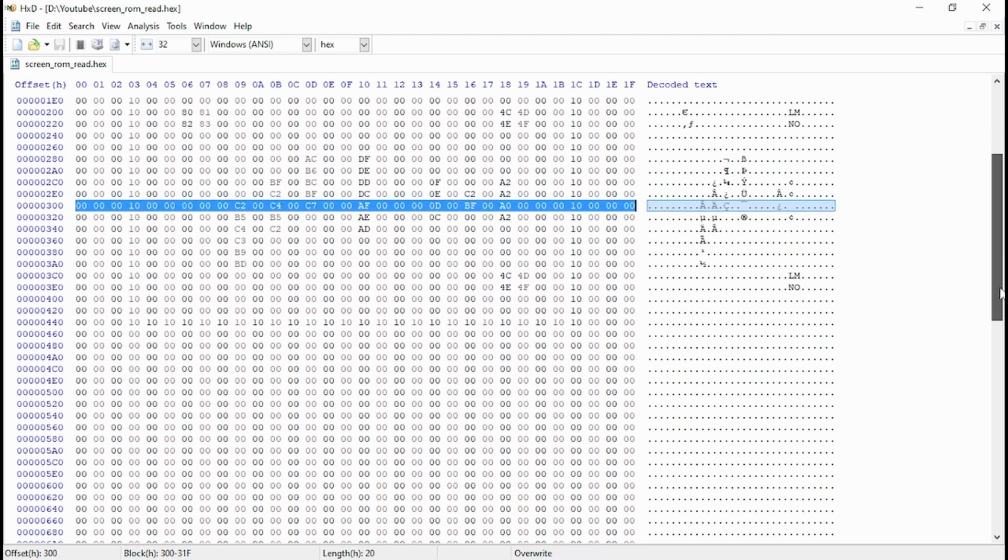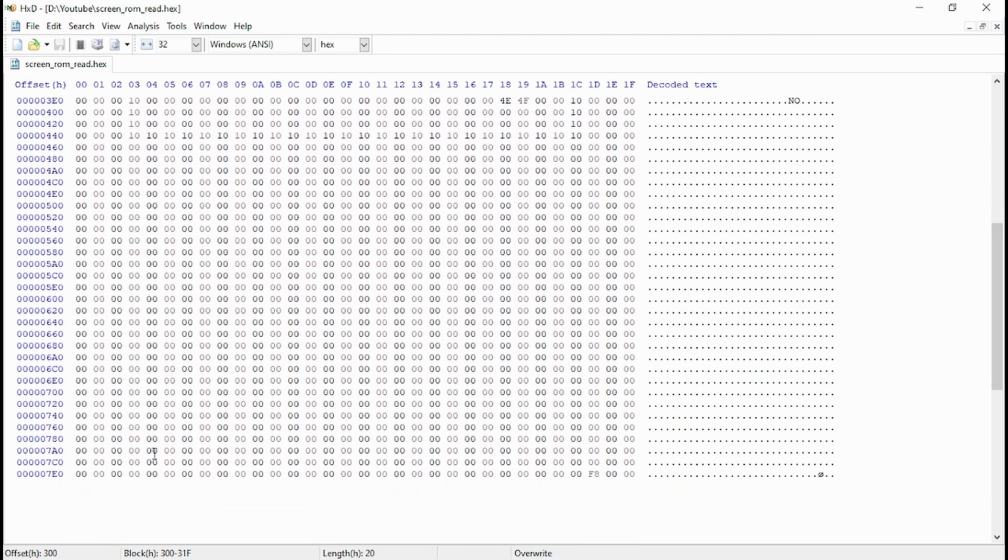Now, one very important addition to the hex file at the end is what's called the reset vector. The reset vector is where the CPU looks when we run the reset sequence. In the case of the 6502, the reset vector is stored at locations FFFC and FFFD. So on a reset, it reads those two locations and gets a memory location for where to start running code. You can see here we have 00 in FFFC and F8 in FFFD.